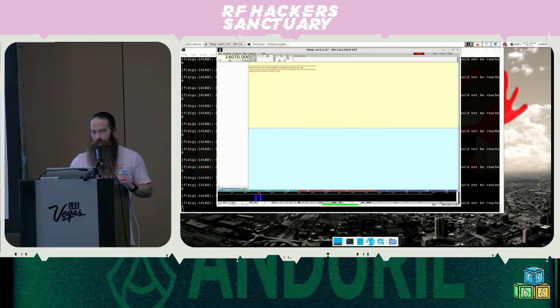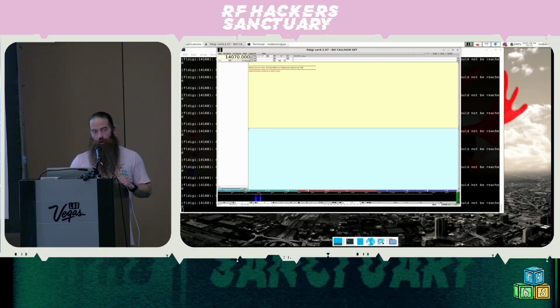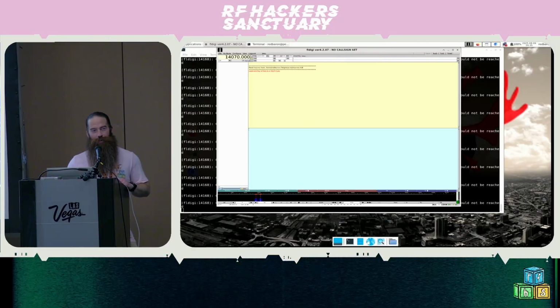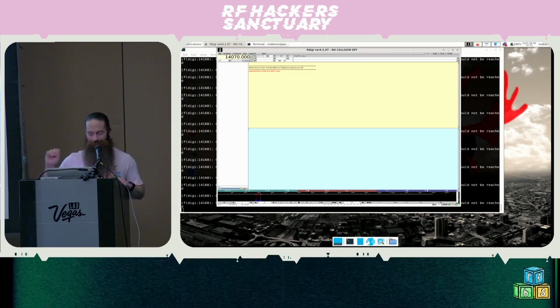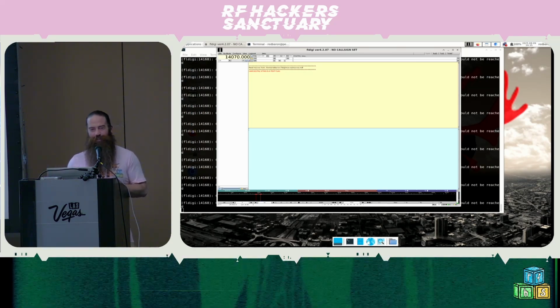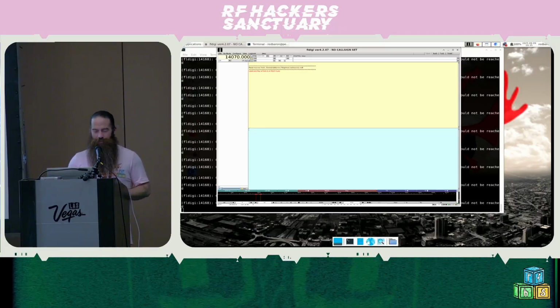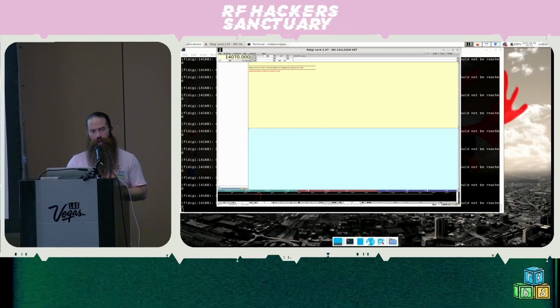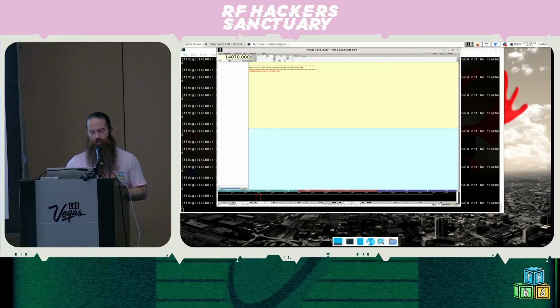If you do that, make sure you double check the sample rate of the audio file and the sample rate that you have set in the flow graph, because that is something that just bit us a few minutes ago. 8,000 hertz, as it turns out, is not the same as 48,000 hertz, but it's easy to miss. But yeah, that's what you need to do for generating new flags for any of the modes that FLDigi supports.